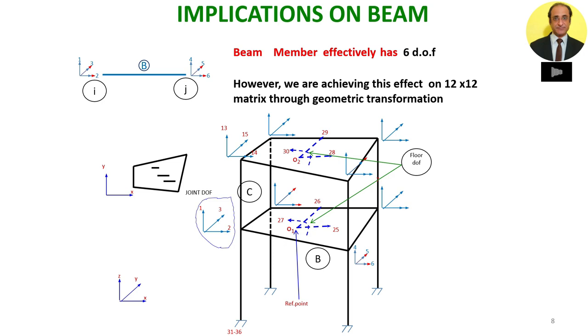So after this transformation, we have seen that the beam does not have any lateral bending moment and axial force. But how about torsion? Will torsion be there or not? The answer is that torsion is not eliminated. The beam still has torsion. If the beam is connecting two columns that undergo different rotations normal to the plane of the beam, then these differential rotations will give rise to torsion. This kind of torsion is called compatibility torsion.